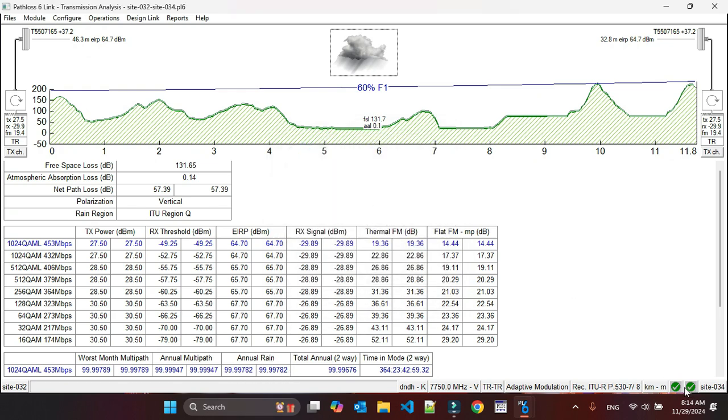And if you see here, these two checks are green. It means that path loss has done its own checks, and based on the checks, path loss says that this link looks to be working fine as per the recommendations which are provided here. So apparently it looks like maybe everything is done, but one thing is not done. What is not done is we have not provided the actual frequency that this link will be using.